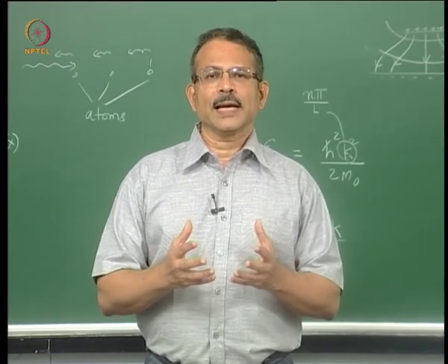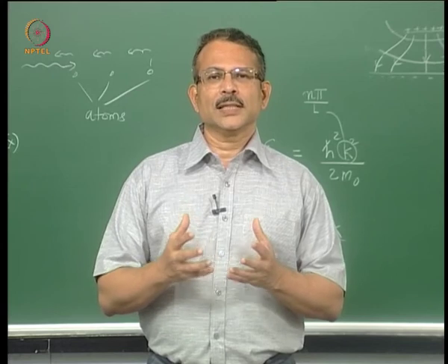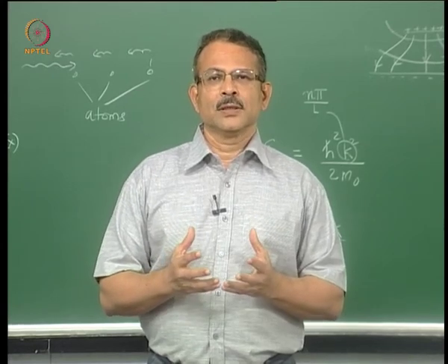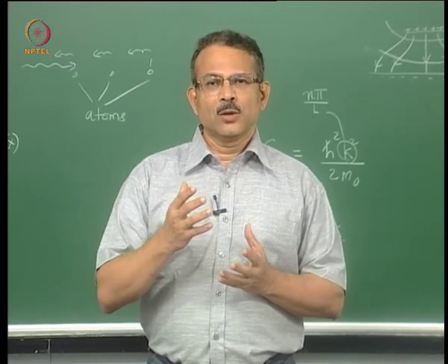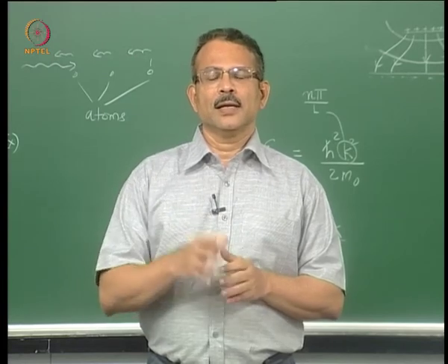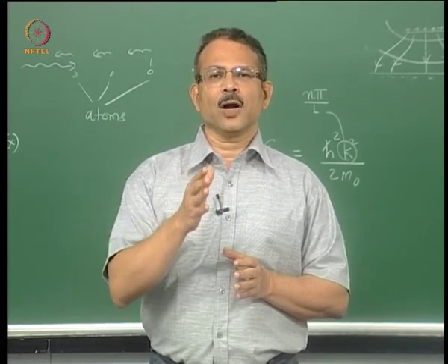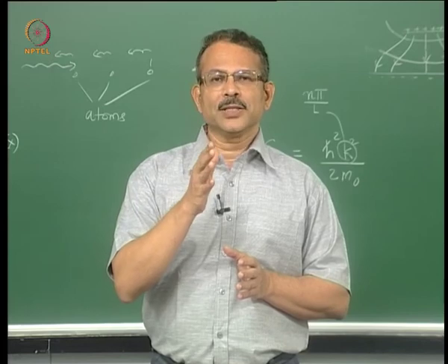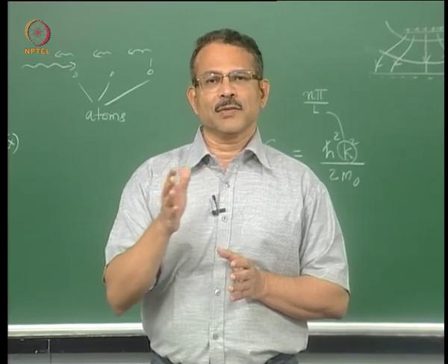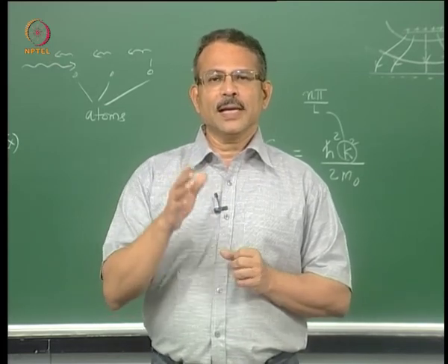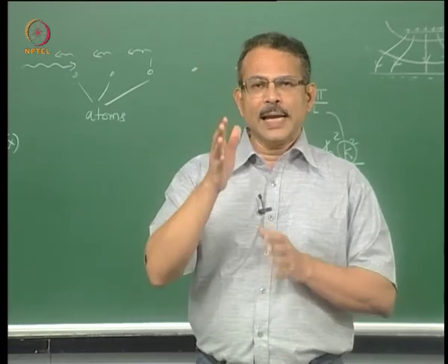It is a very important diagram used in the analysis of devices. The two types of band diagrams are the E-x diagram, where you plot allowed energy levels or energy bands of electrons in a crystal as a function of distance, and the E-k diagram, where you plot at any location